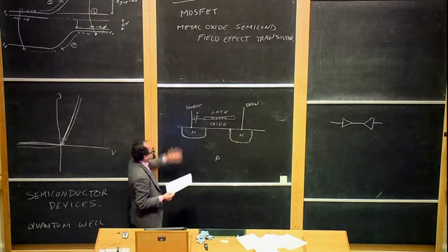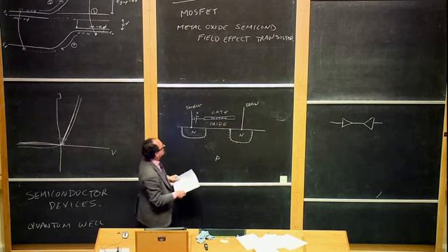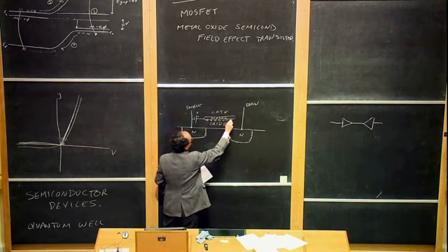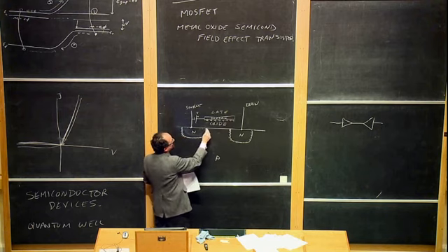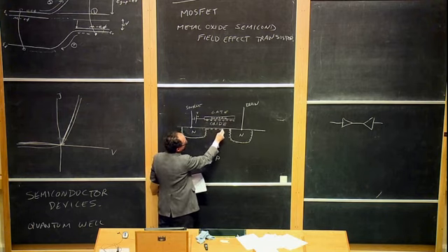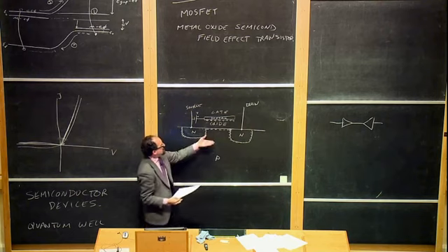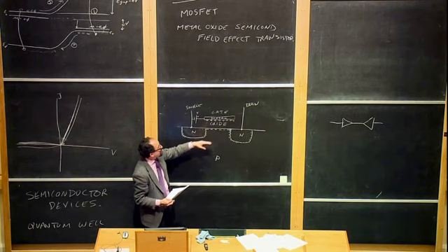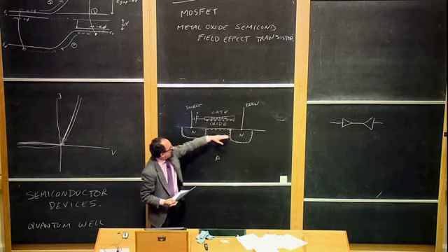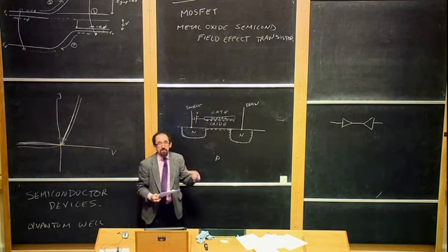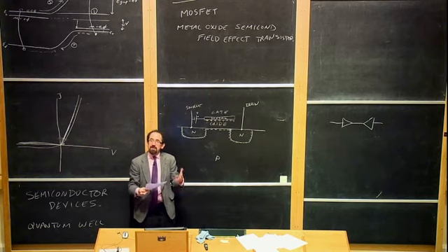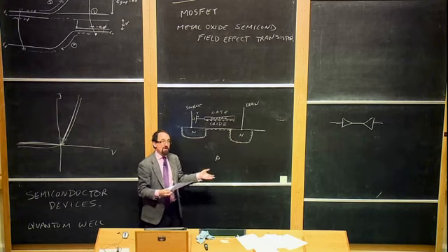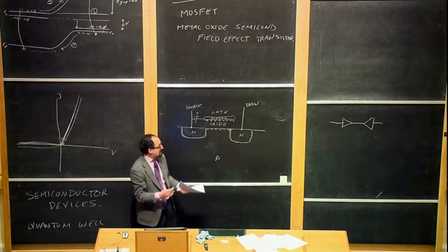All right, so what's the purpose of this metal gate? You charge it up so it has plus charges on it. And these plus charges act like a capacitor, and they're going to attract negative charges on the semiconductor here. So we're basically just charging up a capacitor plate between the metal and the semiconductor. This region here on the top of the semiconductor used to be p-doped. It used to have holes there. But now we've attracted a lot of electrons into that region. So instead of being p-doped, it's now majorly n-doped because we just attracted electrons there, so now it's n.